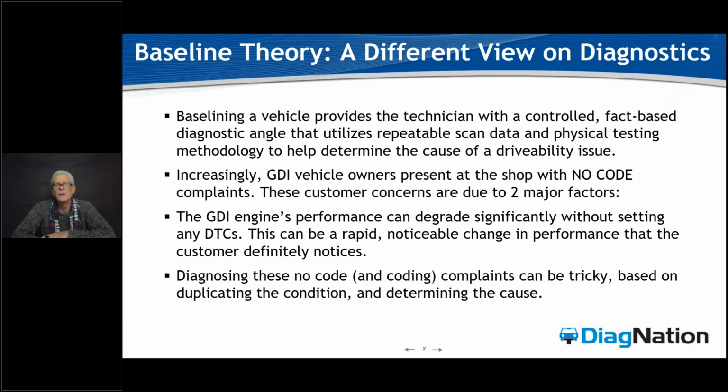But the real issue that we're going to drill in on today is these fuel and oil carbons that are building up in these engines are completely whacking out the OBD2 data over periods of time if nobody is aware of the buildup in the car and nobody's looking for it. I know it's quite common to be selling induction services and carbon cleans on vehicles today. That's not a mystery anymore. It's not a snake oil thing anymore. Everybody knows that chemistry and physical carbon removal is necessary in these cars, okay? But diagnosing some of these ghost complaints can be a real issue, and baseline theory can help us to kind of unlock that.